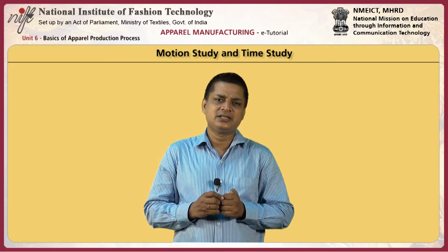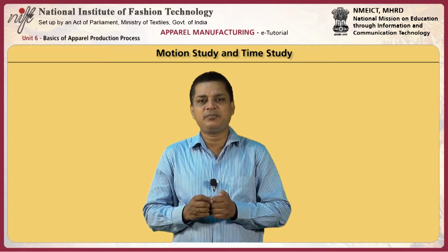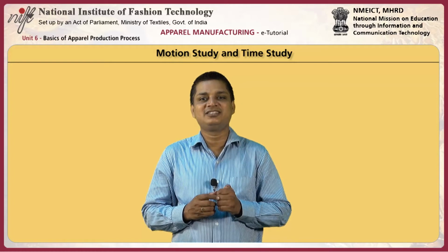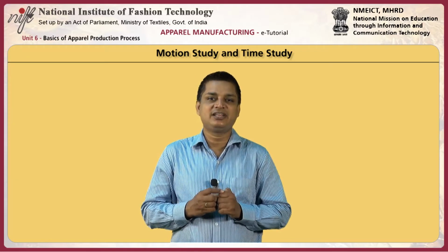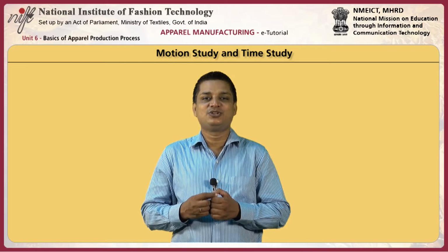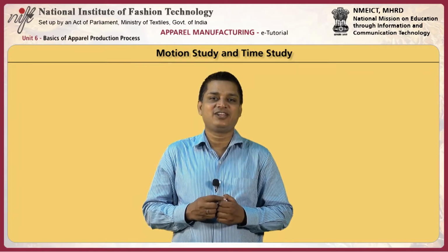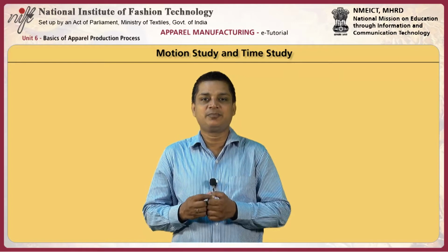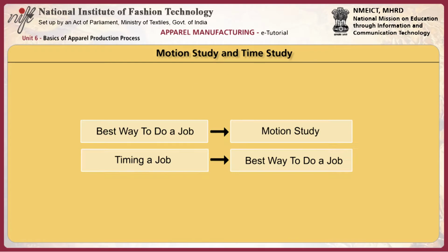When an engineer times an operator, he is performing the second part of our simple definition, the how long does it take part. Before he does this, however, he should study the job to find out the best way to do it, the first phase of our simple definition. These two steps of finding the best way to do a job and then timing to find out how long it takes are referred to as motion study and time study.